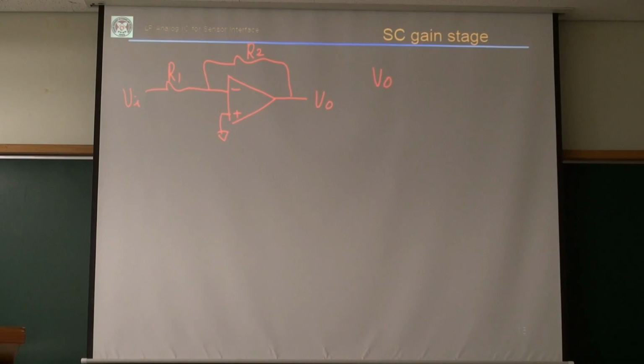The transfer function of this amplifier is just this one, right? If this op-amp has a pretty large gain for all frequencies considered, this resistor will be replaced by switched capacitors.